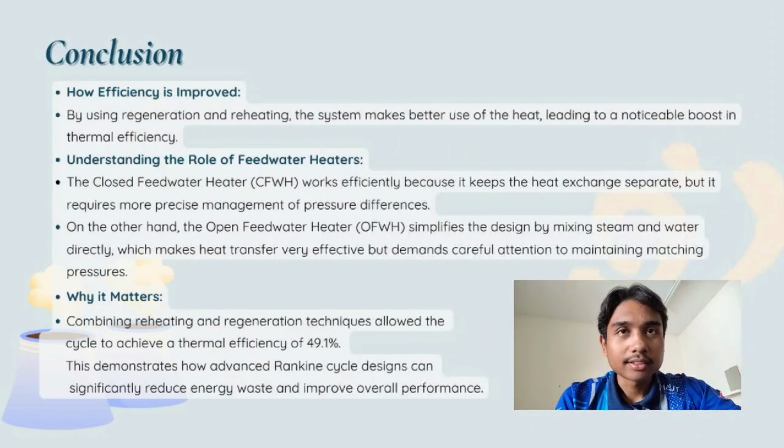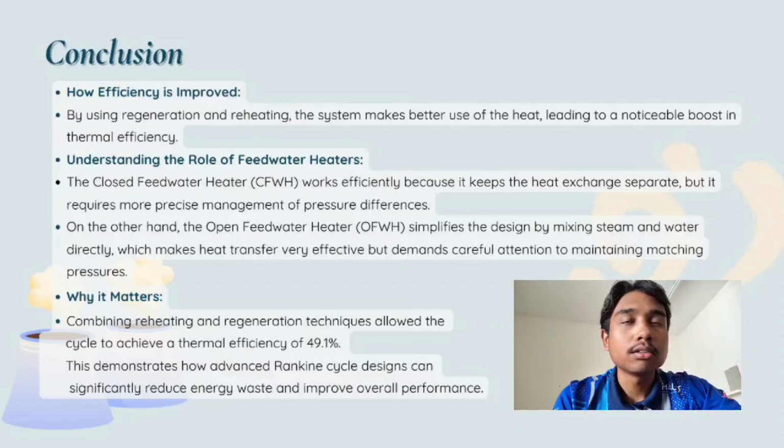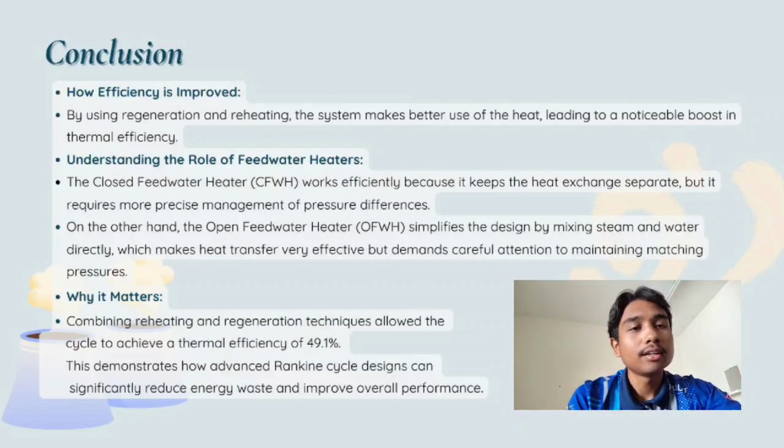So for conclusion, efficiency is improved by using regeneration and reheating. The system makes better use of the heat, leading to a noticeable boost in thermal efficiency. By understanding the role of feed water heaters, the closed feed water heater, known as CFWH, works efficiently because it keeps the heat exchange separate, but requires more precise management of pressure difference.